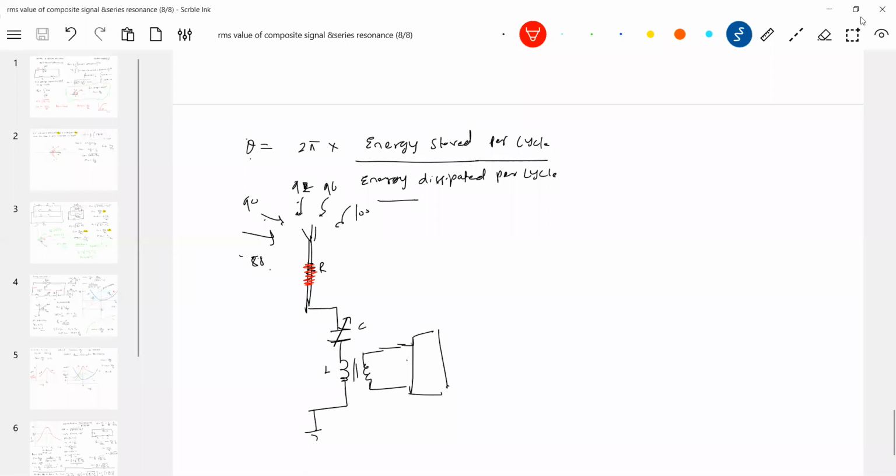Whether you listen or not, everyone will transmit their own programs at frequencies 88, 90 megahertz, 92, 96, 100 megahertz. You want to listen to 92. So what you're going to do is adjust the values of L and C so that you get this. So here you're going to vary the C. Then once the frequency of the circuit becomes equal to 92 megahertz, only that particular station's program will have maximum current.